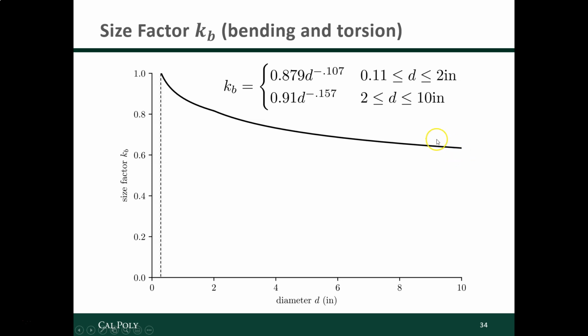Before I give the answer, think about where fatigue comes from. Think about the fact that for a polished mirror finish, we didn't have any cracks on the surface, right? And so we had a Ka of 1. As we had a rougher surface finish, we could have micro cracks on the surface that could grow bigger, and we ended up with a Ka that was smaller than 1. What about the size of the part might affect fatigue then? It's not explicitly explained in Shigley, but it seems to me that if you have a larger part, then there's just more area over which you could have these cracks. There's a greater chance that you could have cracks. So the larger the part, the more cracks there are to begin with, and the lower your endurance limit is going to be as a result.